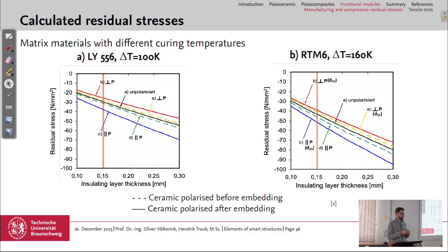And therefore the brittle ceramic, which would fail under tension earlier than under compression, can be stressed higher under tension, and this leads to a more ductile behavior. This enables us to bend the actuators to a curved surface where the ceramic, without the polymer and without the stresses, would just break.